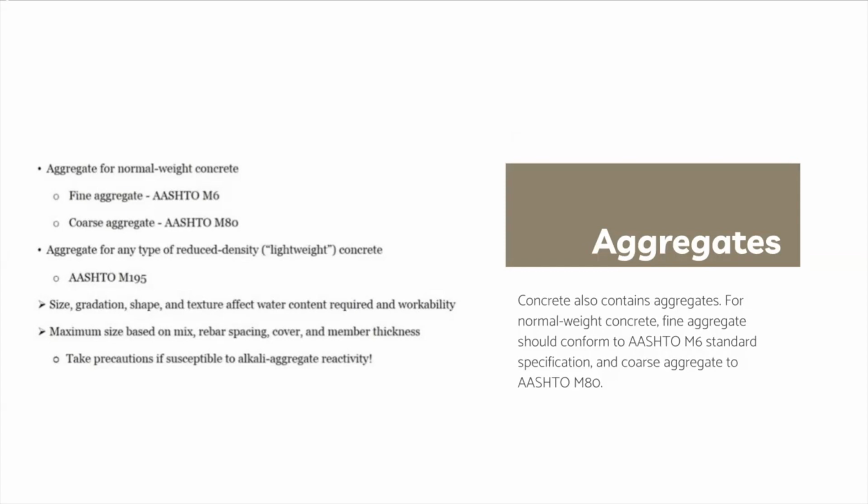Determining the maximum aggregate size depends on various factors such as mix design, rebar spacing, cover thickness, and member thickness. Additionally, precautions should be taken if any aggregates are prone to alkali aggregate reactivity to prevent potential issues.